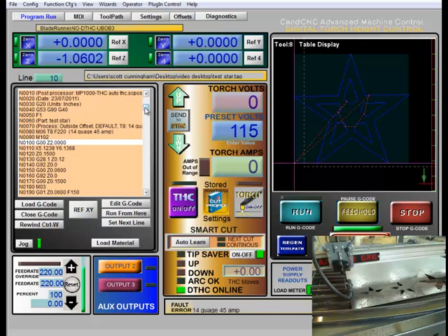You know, this could be... So, since there wasn't a pierce before that, it's actually going back to the very beginning. Okay? So from this position, I could run it from the very beginning and it would start back up. It would overcut this part of the cut that's already been done. However, usually that's not a big problem. Particularly on thinner materials like this, usually you can get away with it.